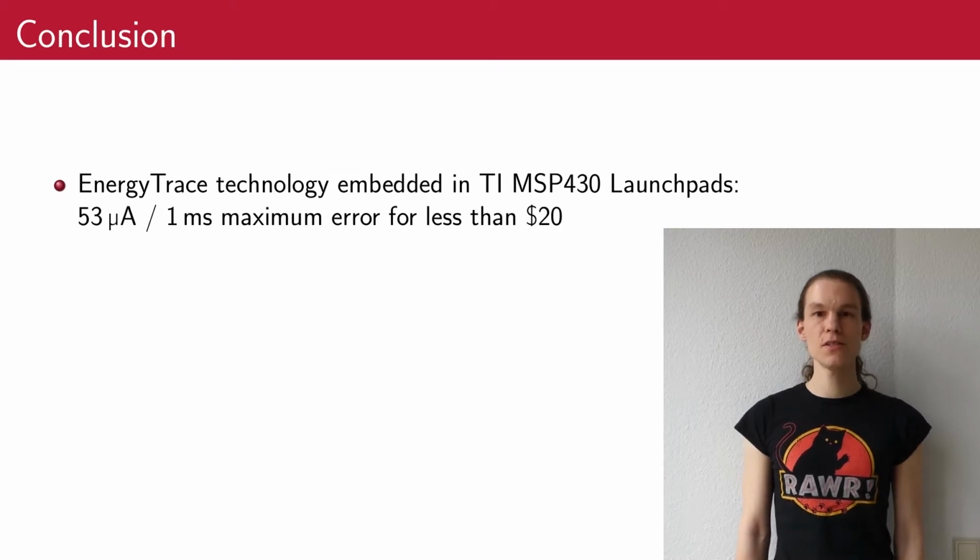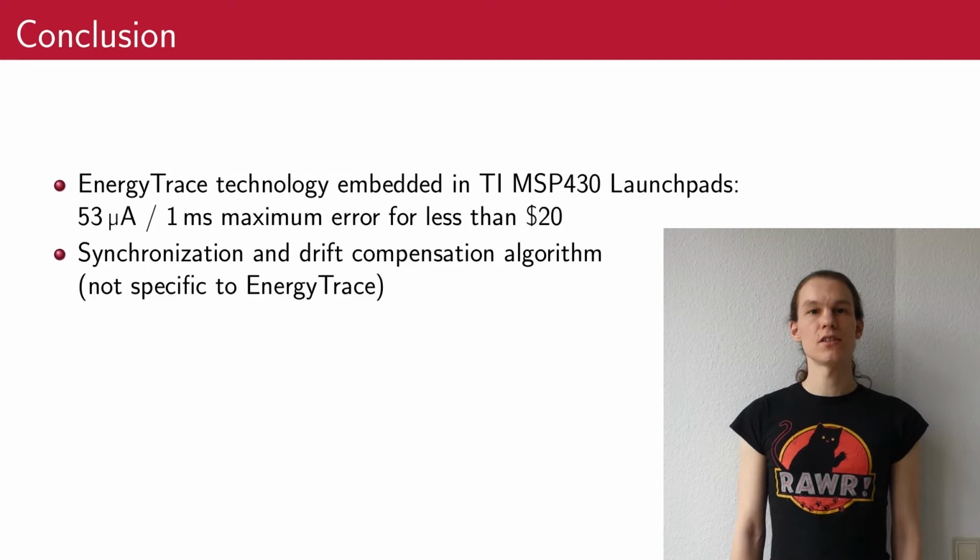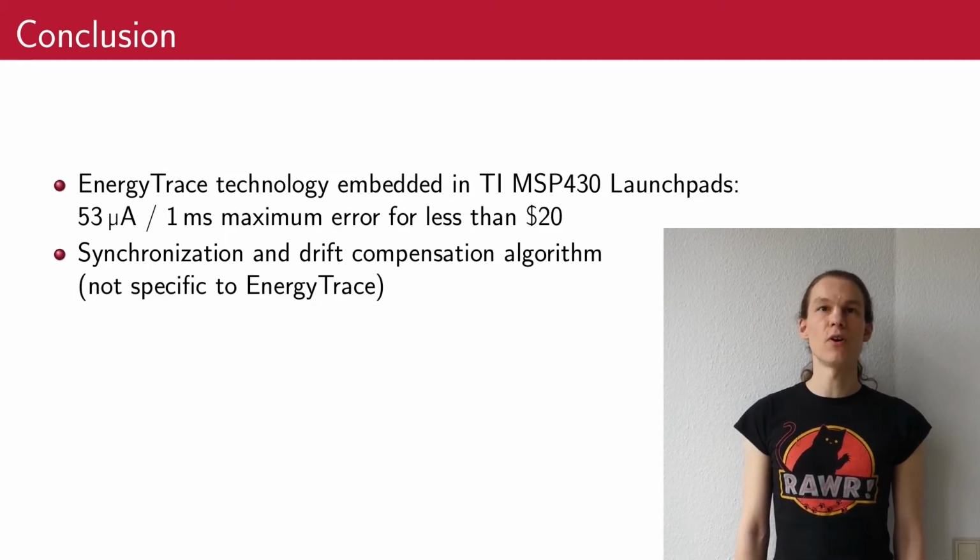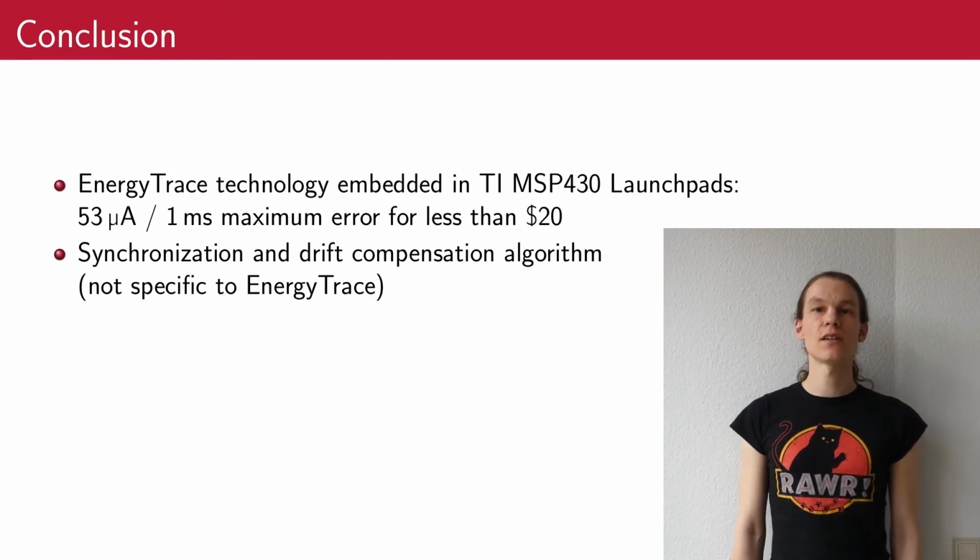In conclusion, I have shown how to use the EnergyTrace technology embedded in TI MSP430 Launchpads for automated measurements with acceptable accuracy figures and a cost of less than $20. I've also presented a synchronization and drift compensation algorithm which are not specific to EnergyTrace but applicable to a wide range of devices which lack conventional synchronization mechanisms.